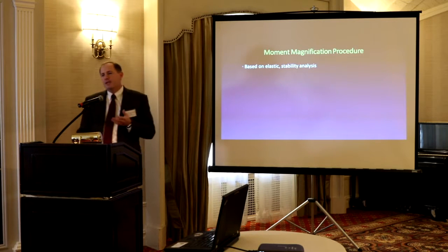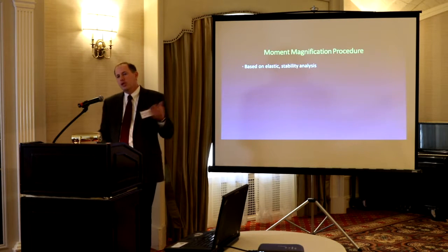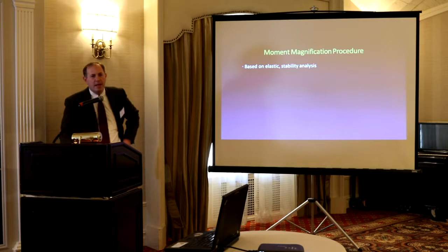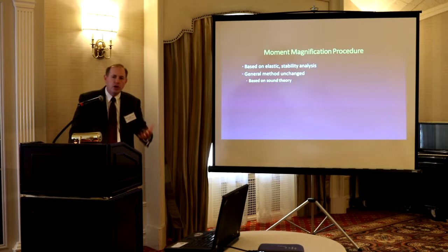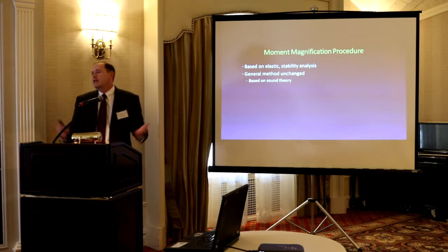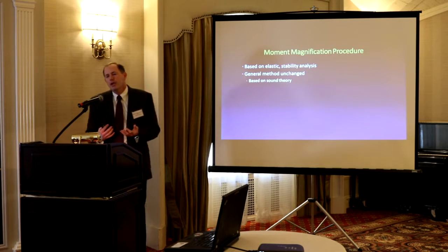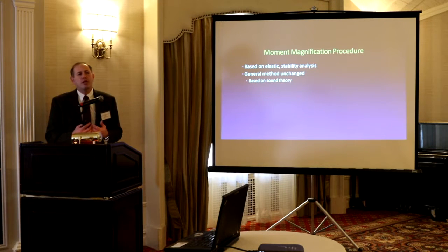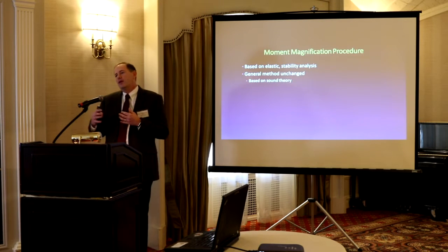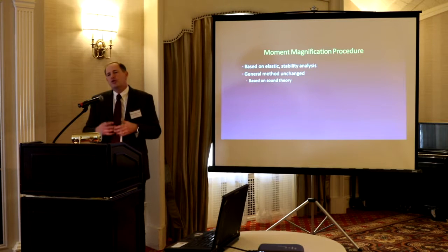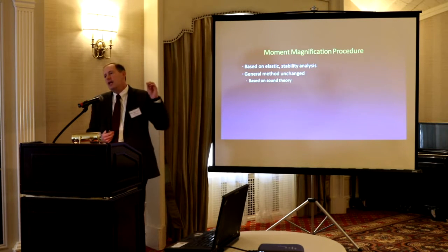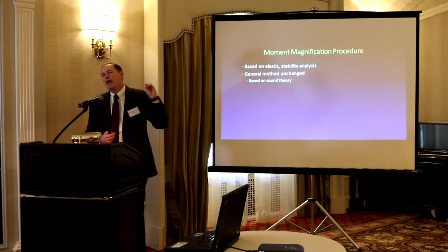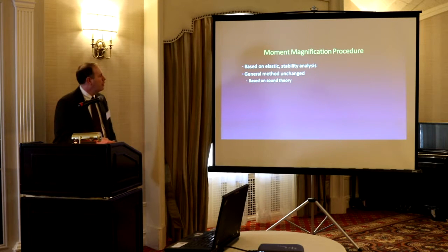It's based on elastic stability analysis. Timoshenko, if you go back and look at some of that, this is very classical type work. The general method that we're going to talk about, what's in the code today, has remained unchanged. It turns out that's a great method. There's a simple equation that's looking at small deflection theory. It doesn't mean that they're that small, but it assumes small deflections and a shape, a sine wave, for the deflected shape, and unless you're right near the buckling load, the answers are very good.